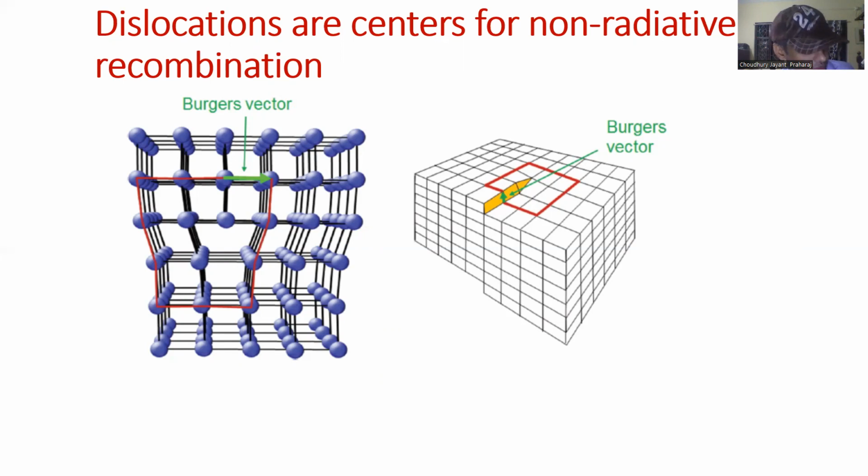And as we saw in some previous slides, the dislocation densities can be affected a lot by the substrates that are used. For example, silicon carbide substrate or silicon substrate or sapphire substrate can lead to different kinds of dislocation densities. And also the growth conditions can affect the dislocation density. So those need to be optimized for obtaining good solar cell performance.